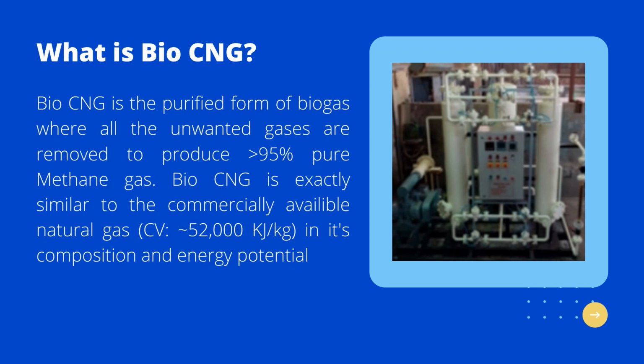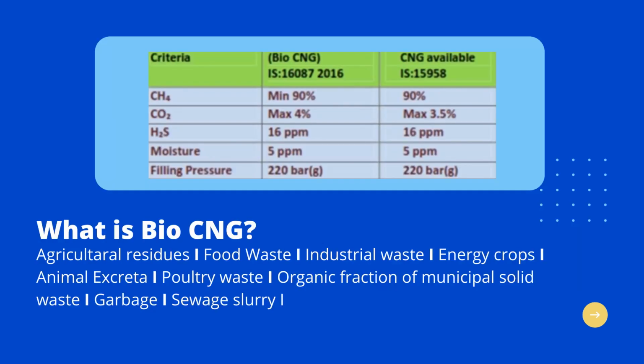Non-polluting. What is bio-CNG? Bio-CNG is the purified form of biogas where all the unwanted gases are removed to produce 95% pure methane gas. Bio-CNG is exactly similar to the commercially available natural gas, CV approximately 52,000 kJ per kilogram, in its composition and energy potential.